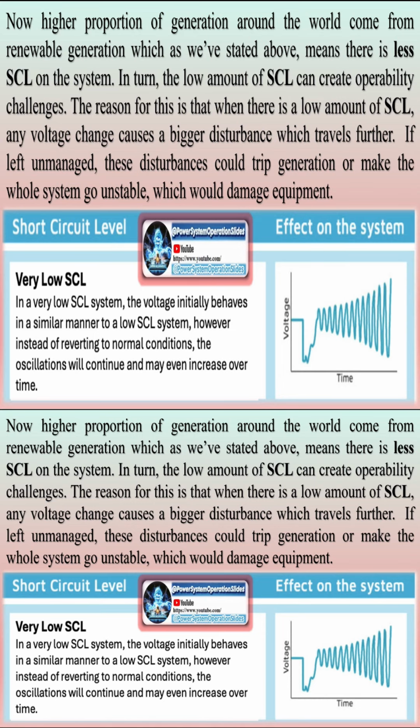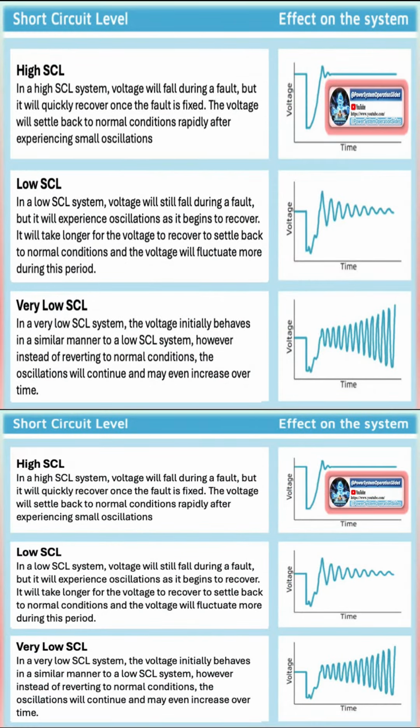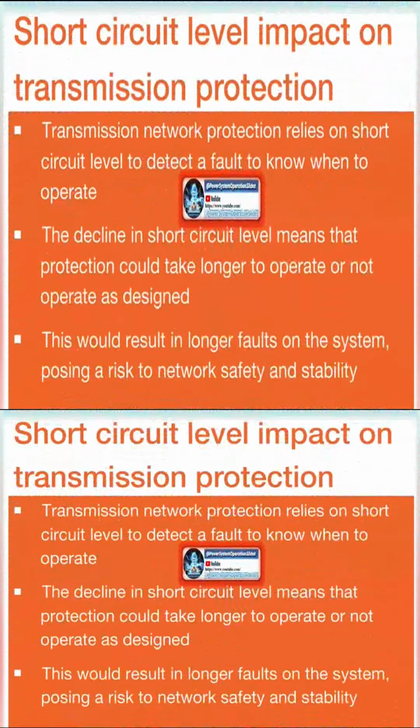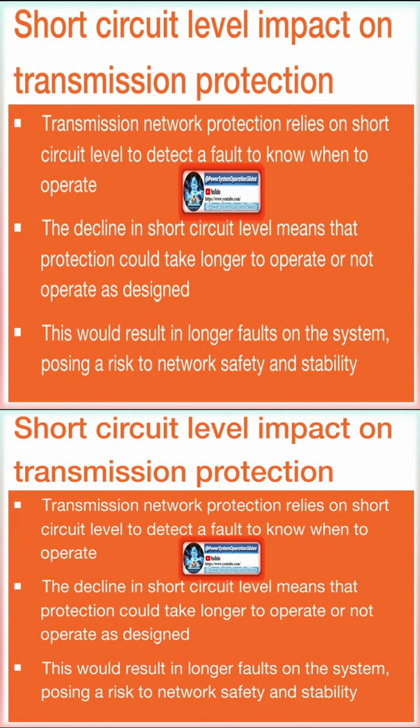If unusually high currents exceed the capability of protective devices, fuses, circuit breakers, etc., it can result in large, rapid releases of energy in the form of heat, intense magnetic fields, and even potentially as explosions known as an arc blast. The heat can damage or destroy wiring, insulation, and electrical components. An arc blast produces a shock wave that may carry vaporized or molten metal, and can be fatal to unprotected people who are close by.